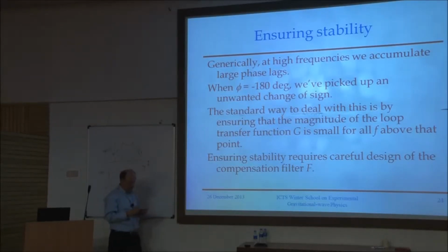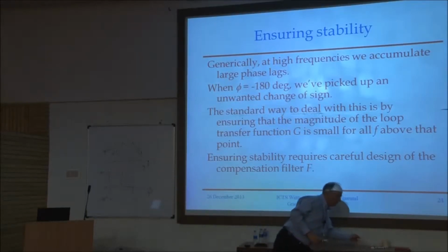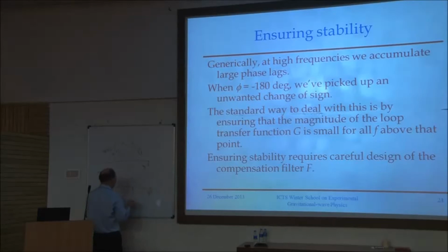And at that same spot, I should carry around all of these. Where I was just barely skirting minus 180, boom, I can have another minus 180 from that resonance. And when that happens, almost always, the system goes unstable. And this is the form of instability where it starts to scream at this frequency. And this is generic. If you're trying to make mechanical servos all the time, you're running into actuator limits like this, to unmodeled resonances.